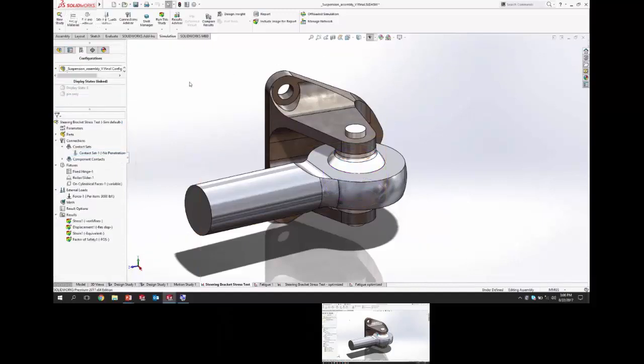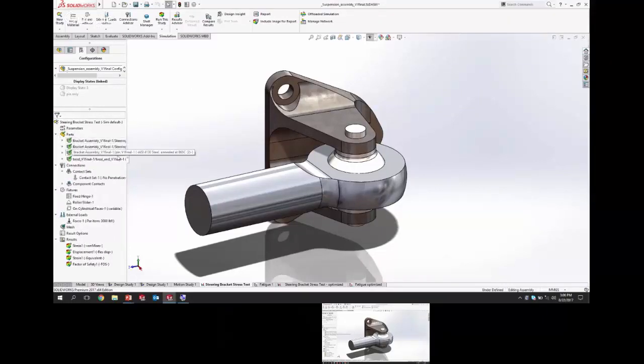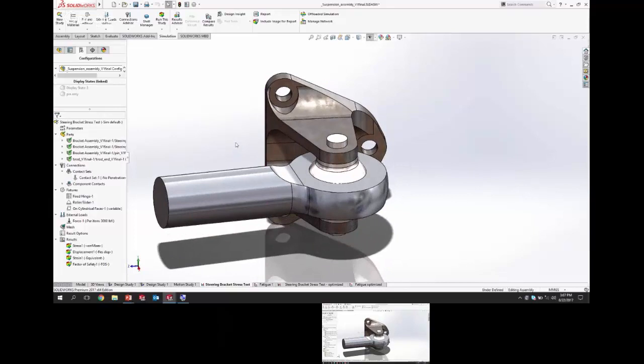And you'd asked, I apologize for forgetting your name. It was Jeremy. Yeah. You'd asked a little bit about what makes an assembly analysis different than a part. And it's largely those contacts between the components that can make a big difference. Obviously the materials, right? Because in an assembly, each body in the assembly or each body in a multi-body part can have different material settings.